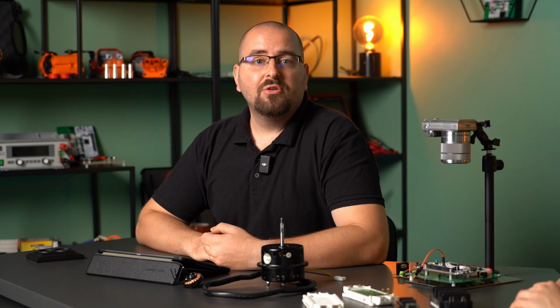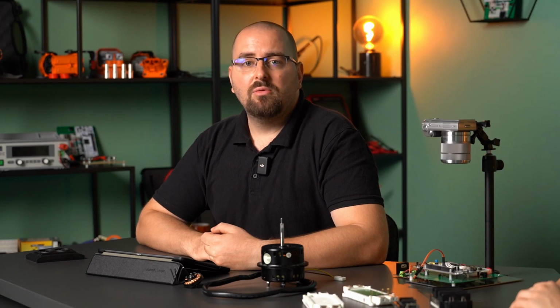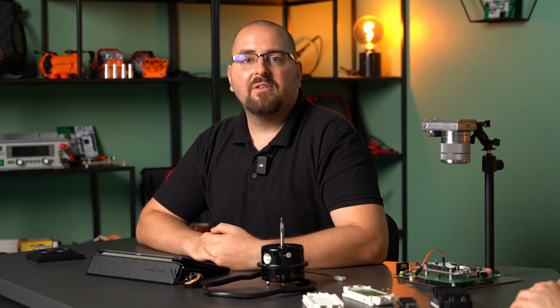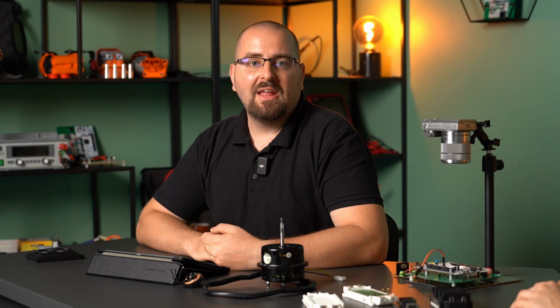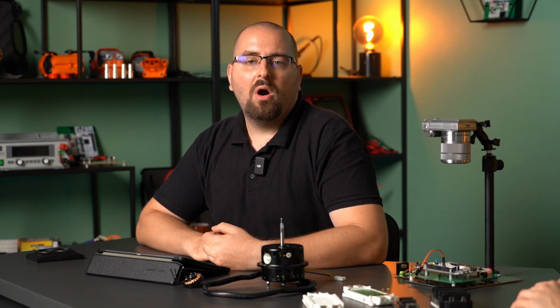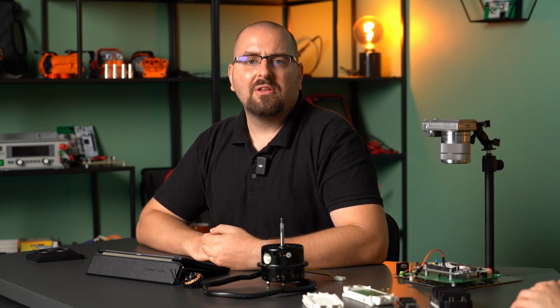Another advantage of electrically commutated motors over mechanical ones is that they are more efficient, meaning they convert electrical energy into mechanical energy more efficiently. One of the obvious reasons for this is that they do not contain carbon brushes, which cause losses through friction, and the current conduction properties of the carbon brushes are below the same parameters of an electric commutator.